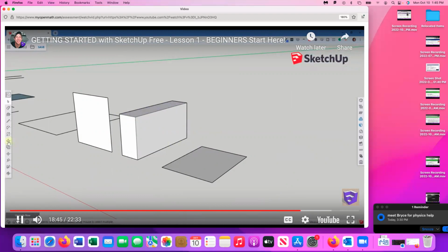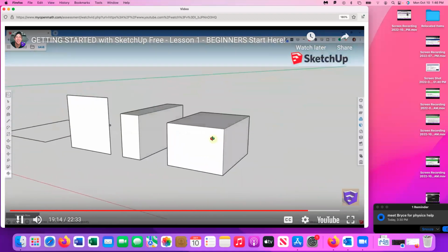And what the push-pull tool does is it takes a face like this one, and it extrudes it into 3D. So by activating that tool, either by clicking on this or tapping the P key on your keyboard, you can mouse over a face, single click, and move your mouse in order to extrude this into 3 dimensions. And so basically it's taking this face, moving it up, and then filling in the geometry around all the different edges to make this a 3D shape.